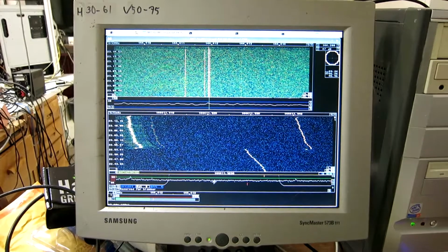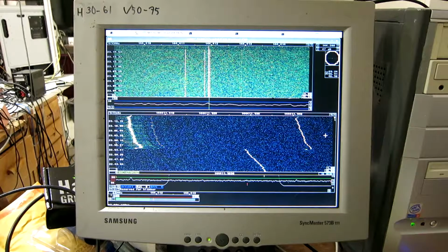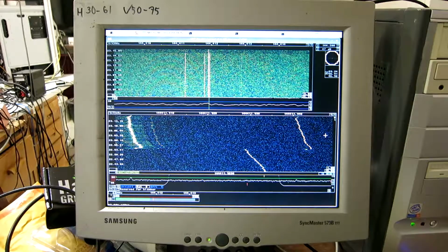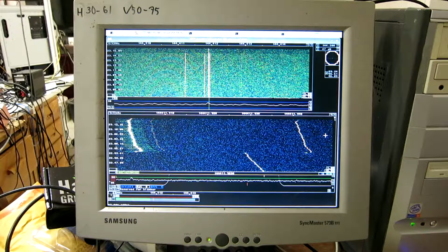You can see the instabilities here. That's the phase noise. The signal is not really as narrow as the resolution of the FFT. But a more stable receiver than this dongle would make the signal more visible and would allow some averaging to make it stronger, and maybe it would be possible. Yes, it would.